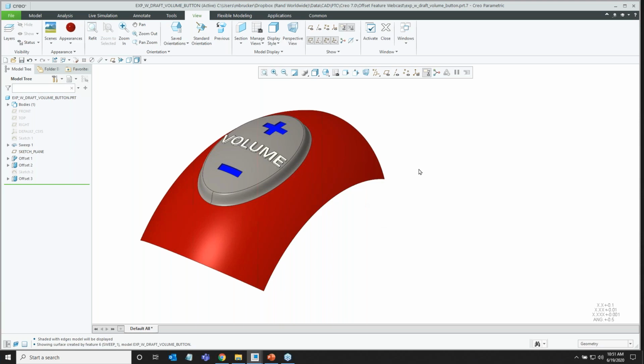All right, so anyways, there's an example where we did a bunch of those offsets inside of a sketched region using the expand. Now, that expand feature works on surface geometry like we looked at here, or on that previous model, we saw that we could take an entire solid face and we could expand that as well.